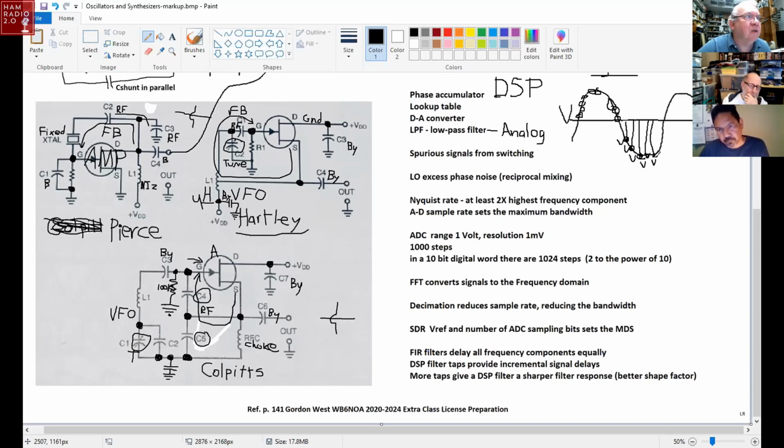You use an oscillator, such as any of these oscillators over here, or other types of digital oscillators, and you run this to a D to A converter. Out comes your sine wave, represented by the mathematical value of the voltages at each step along the sine wave, and this is called the sampling frequency up here. The frequency you sampled the sine wave at is the sampling frequency.